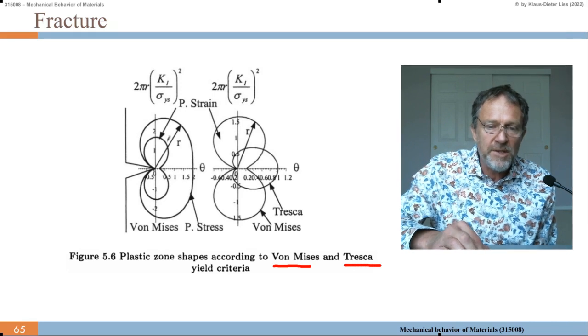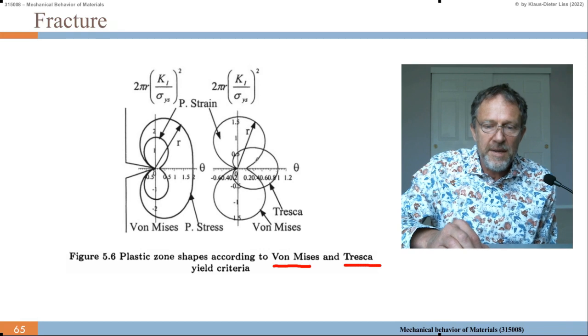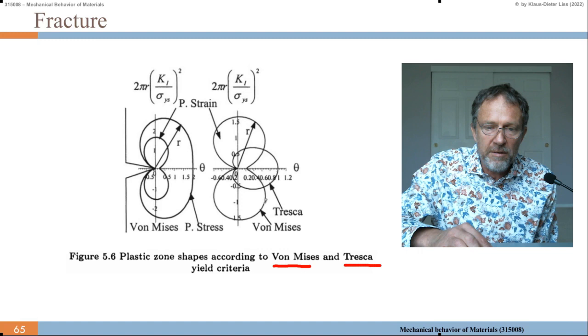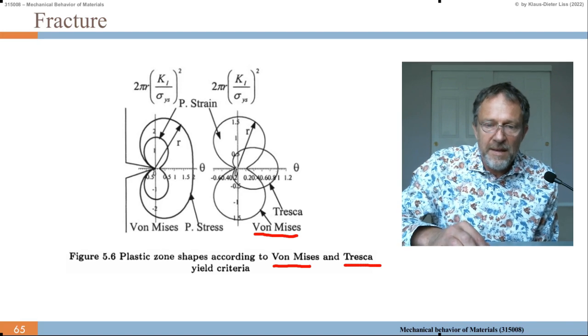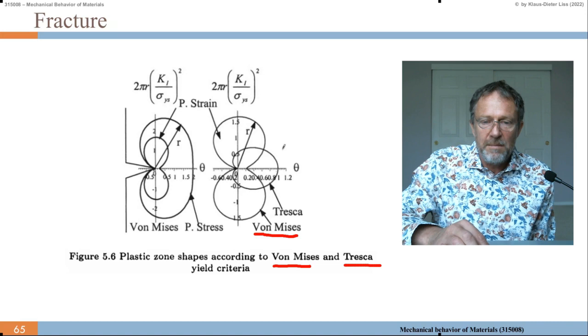Now let's just look at the plane strain situation under von Mises and Tresca. So this little dongle is magnified here. You see 1.5 is here, 1.5 is there. So it's the same curve as the inner plane strain curve, recopied to that figure, magnified von Mises. And we have then in comparison the Tresca criterion. With the Tresca criterion, this plastic zone shape is smaller and more forward oriented.